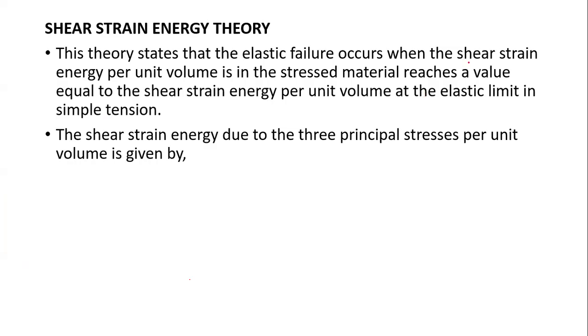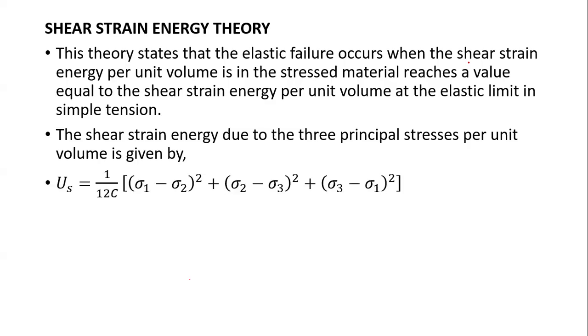So if the shear strain energy per unit volume reaches that value or close to the value at the elastic limit in simple tension, then the material is going to fail. And of course, just like the other one, we have an expression because this is also a three-dimensional stress system.